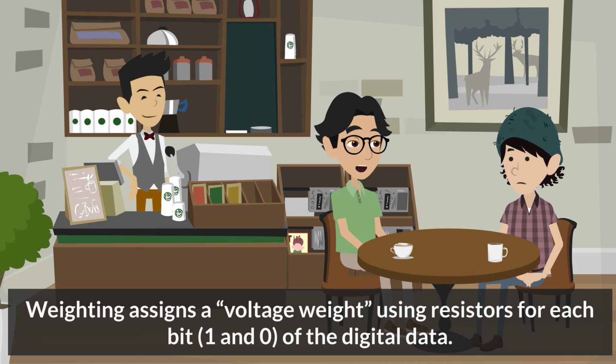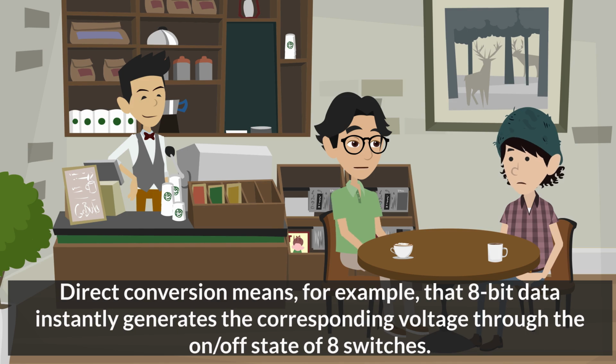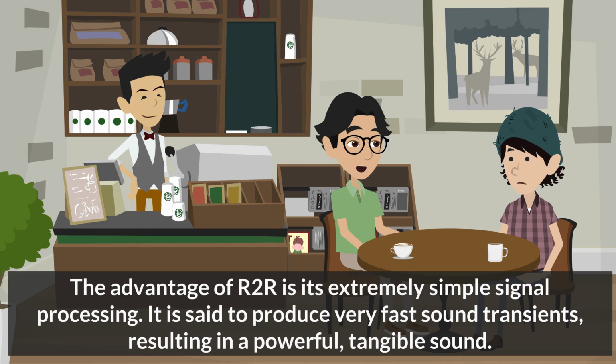Weighting assigns a voltage weight, using resistors for each bit, 1 and 0, of the digital data. Direct conversion means, for example, that 8-bit data instantly generates the corresponding voltage through the on/off state of 8 switches. The advantage of R2R is its extremely simple signal processing. It is said to produce very fast sound transients, resulting in a powerful, tangible sound.